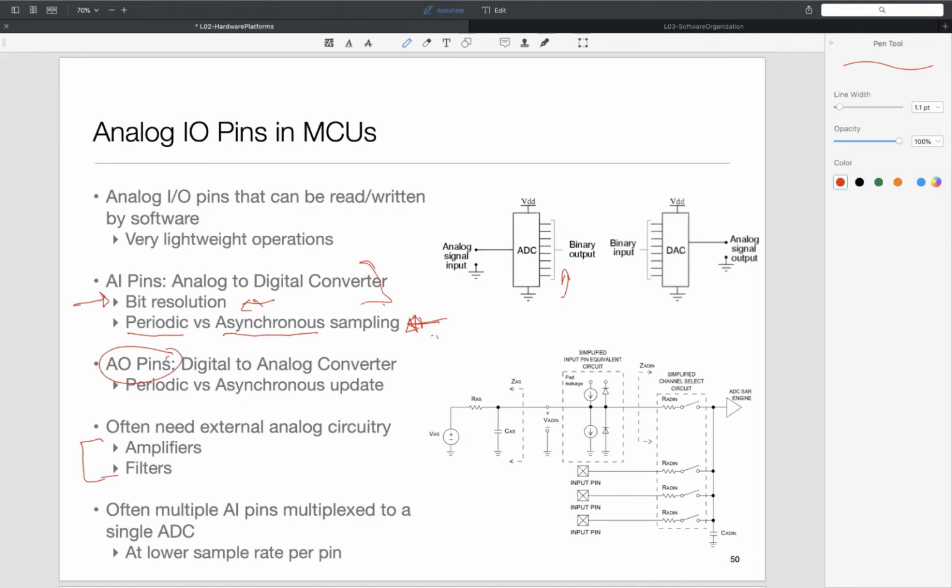For example, if you are feeding input to the A to D converter, and one of you just said we sample at twice the maximum frequency, how do I make sure that the incoming signal does not have more frequency than I thought it would? If I'm sampling at, let's say, 100 kilohertz, then I need to make sure that the signal didn't have frequency more than 50 kilohertz. Usually that's the job of analog circuits. They filter things away. It's something called an anti-aliasing filter. So there's usually this analog circuitry sitting around in a lot of embedded processors, built in to do so.